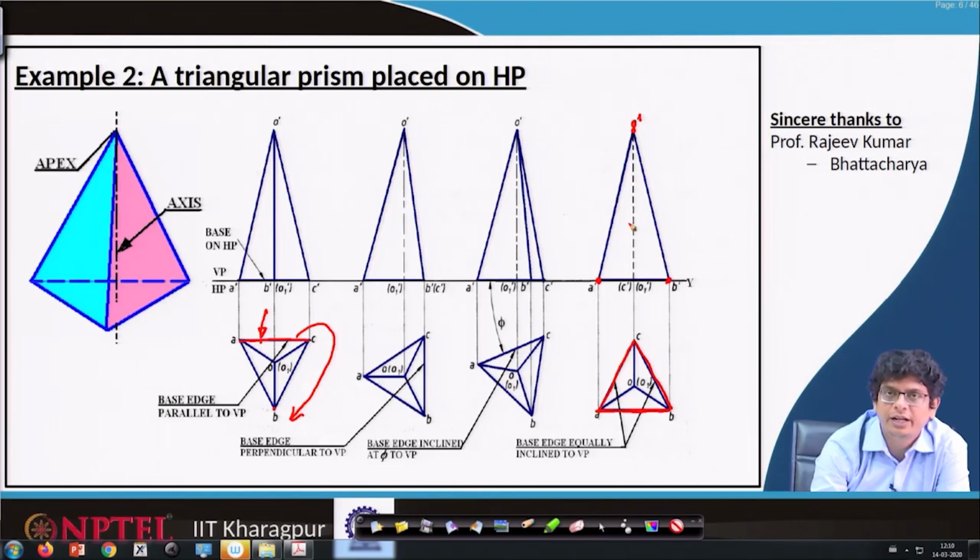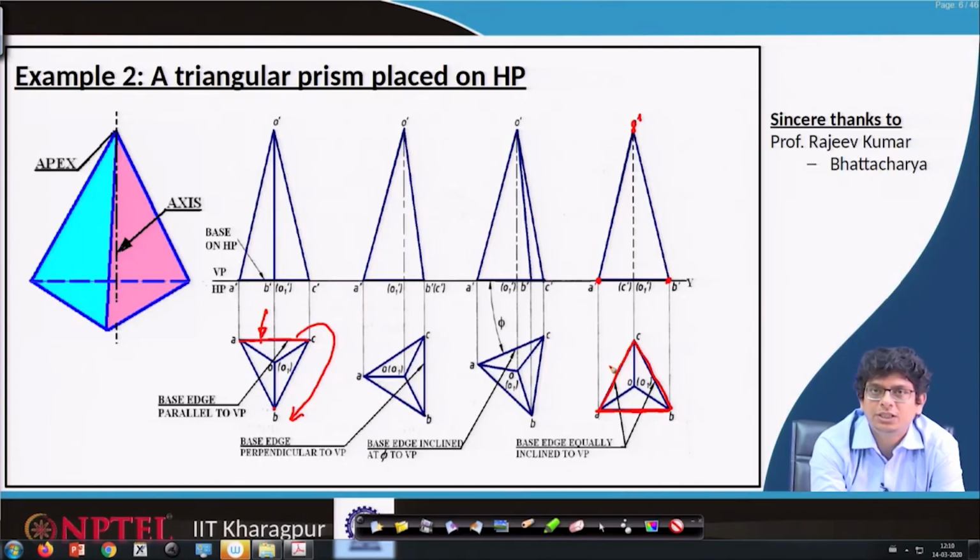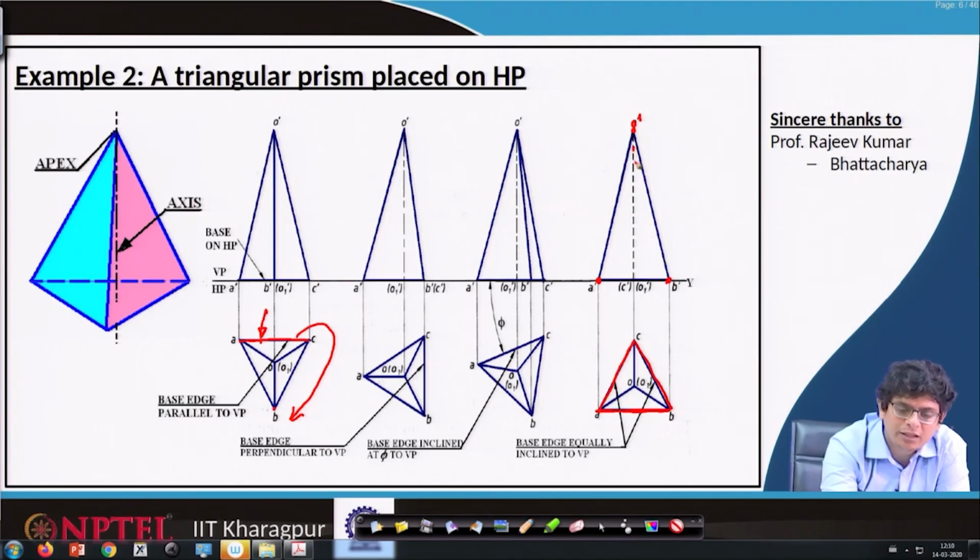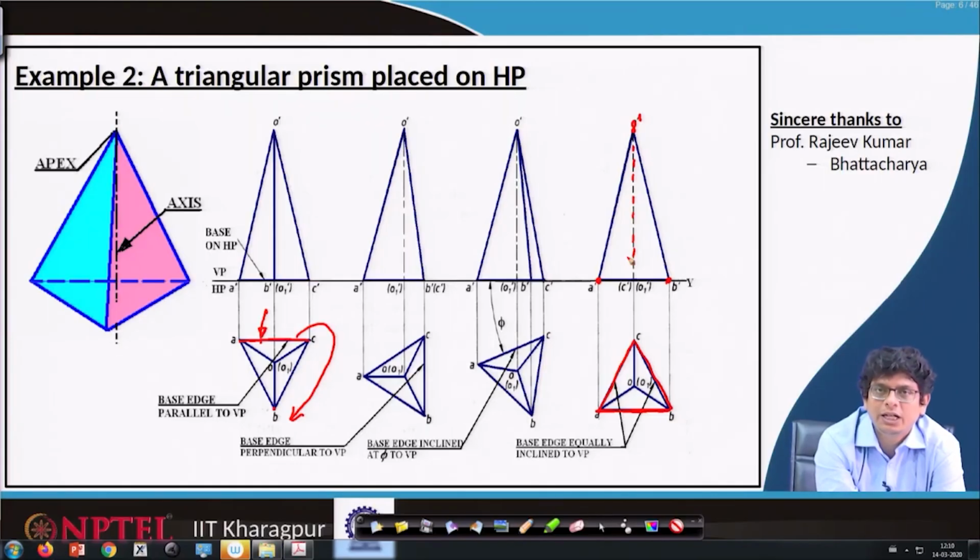If you note it carefully, here the OO1 is supposed to be dash dot lines, but the object dimensions are more important than that axis in this case. So, that C all the way from O to C, whatever invisible line, we show it by dashed lines. So, we do not show that axis and give preference more for this invisible dimension than for the axis.